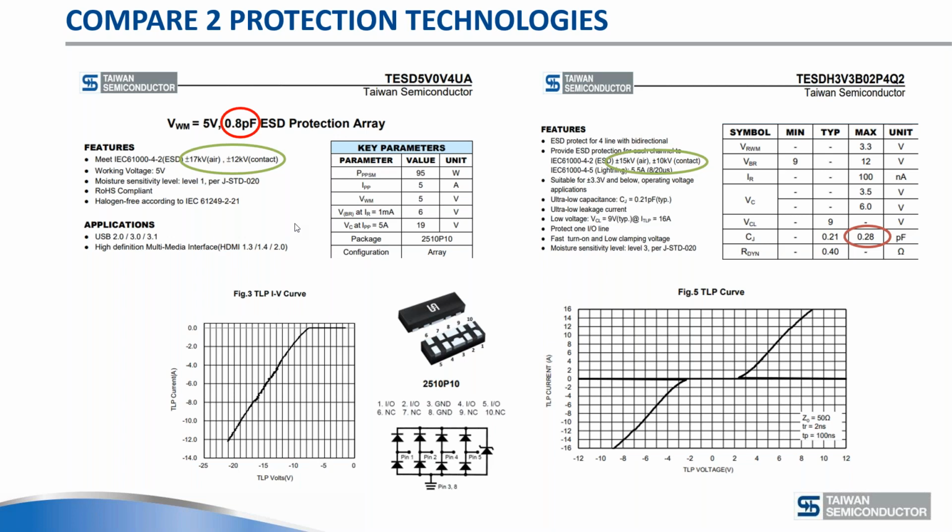But there are two other things that help this technology. The first one is, of course, again, the snapback technology. What it means is that for the same power, you're dissipating less energy, and you can make the die smaller, and also reduce the clamping voltage. And of course, a bidirectional device has two capacitances on 0. This one is bidirectional, and this one is unidirectional. So the bidirectional device is two capacitors in series. That means you halve it, or close to half it in that case. So there are tricks to further reduce the capacitance, but we are getting close to the limit.